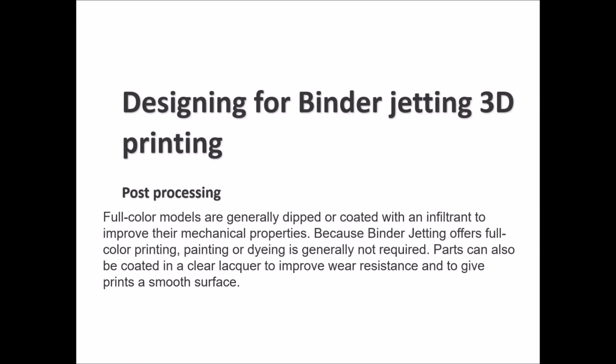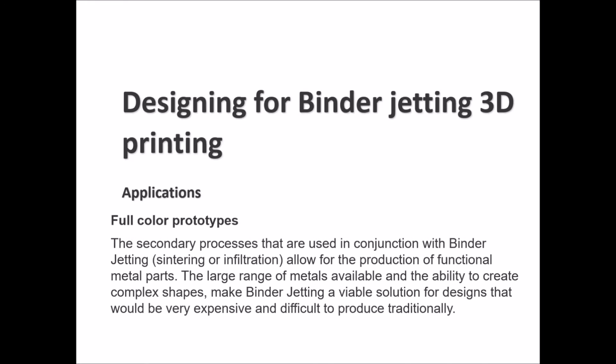So you are just treating a metallic part. You can do all kinds of post-processing done for a metallic part as long as these materials will not degrade the original 3D printed part. Just make sure there's compatibility, then you can do any kind of metal coating on it that will give it a longer life and better mechanical properties.